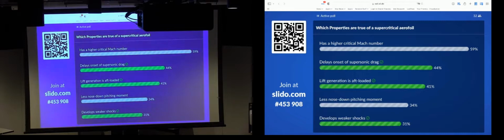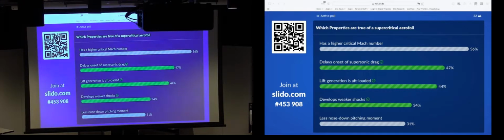If it's over a larger distance, where we have high pressure over there and low pressure over there, what do we get? Yeah, you get wind, you get flow. So if over a long distance you get flow, that equalizes it. Over a short distance, you get a shock wave, a bang. So it has to be subsonic when it comes off the wing.